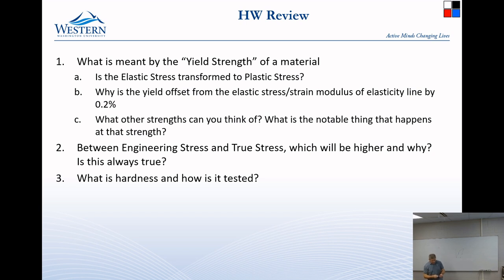Ideally, it would stay exactly parallel, but materials aren't ideal, so it won't be quite exactly the same because other things go on. Ideally it would come back, and then if you wanted to load it again, you would load it back up this curve, and then it would continue on the plastic strain curve, just the way it was going to before.